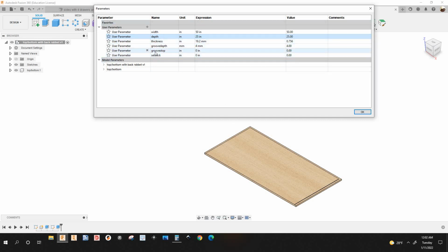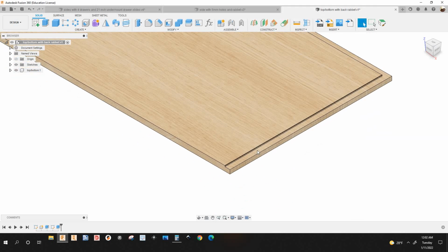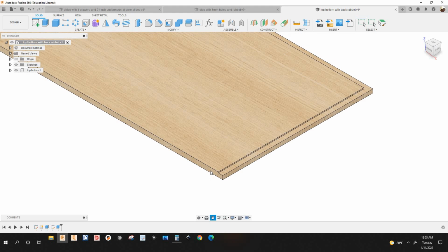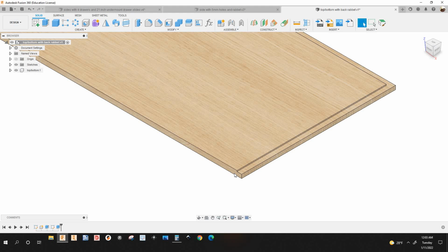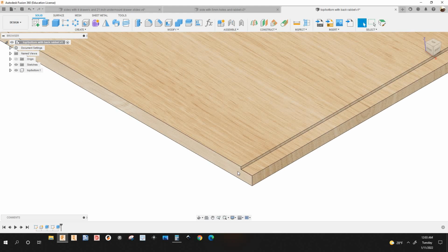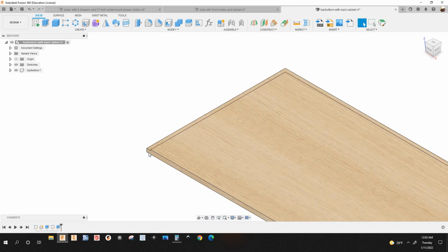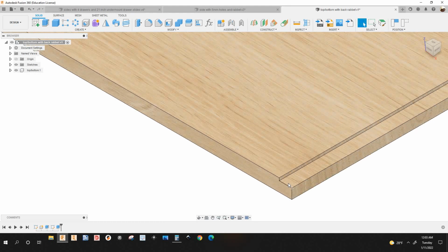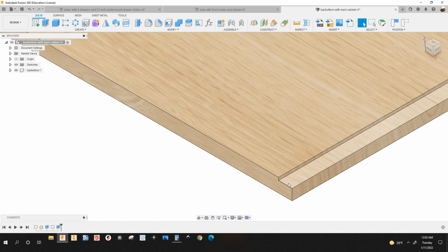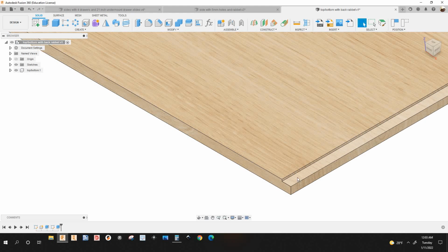You see, I have a parameter called group stop. Right now it's set to 0. Let's say you don't want to machine all the way out because this front edge is edge banded, and your machine does have a tool changer. So you can now use a right-handed tool and a left-handed tool. So let's say you want to stop 1/8 of an inch, or a quarter of an inch, or 5 millimeters, whatever distance you want.